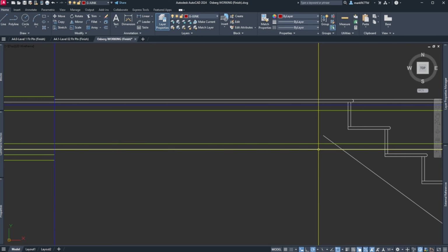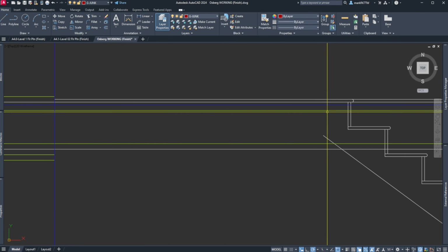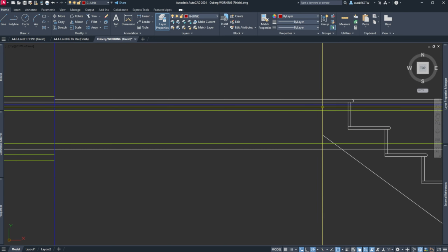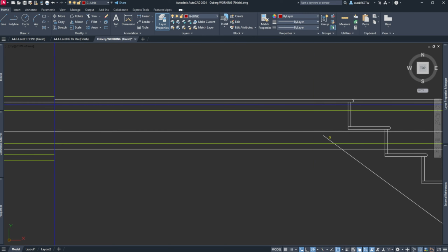And so here, where's my tie-in going to be? Now, let's just say we use a 2x8 hanger. So I'm going to offset 8 inches, because they're not 8 inches tall. And that means it'll sit underneath this. I'll have to cut a joist here, and you have to make a hole for the stair, and then run a member between the two spaces. And we'll see that more when we get up into the plan views and stuff.